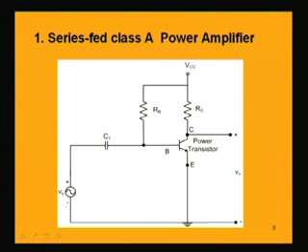The signal which is to be amplified is Vs, and there is this capacitance C1 to couple the voltage Vs, and the reason for the capacitance C1 being used we all know. It is a capacitor to block the DC component, because a capacitor is like an open circuit to DC, and the output is V naught, say, that is going to be used finally.